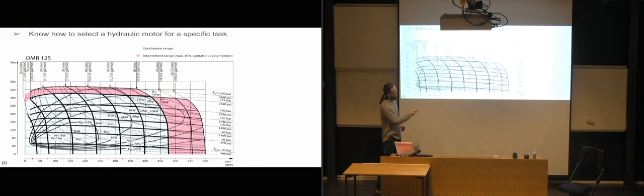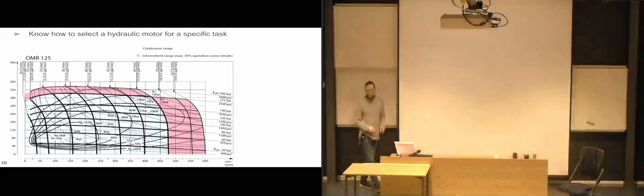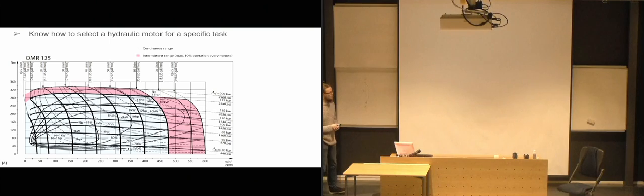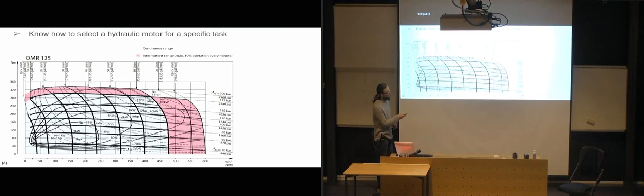Also, when we're over here, we are going to have approximately between 6.5 and 7 kilowatts of power going out of this one. So we have to take into account the amount of power that we're going to have going out of the motor. We also need to look at it being within the 75% efficiency range. So the power that we are getting out, those 6.5 kilowatts, is just 75% of the power going into the motor. So we need to calculate how much we are going to deliver into it.